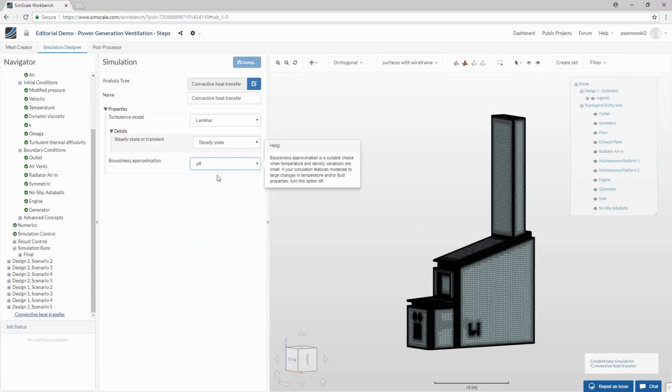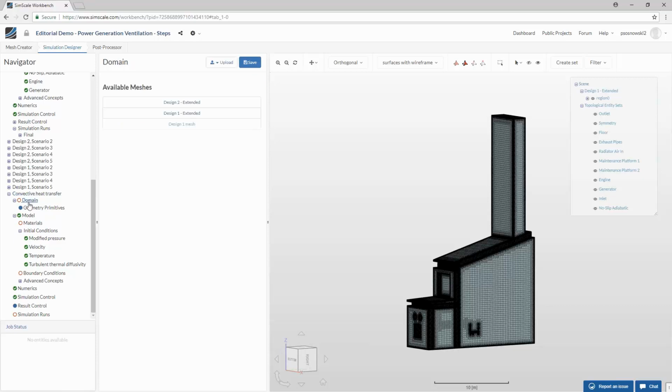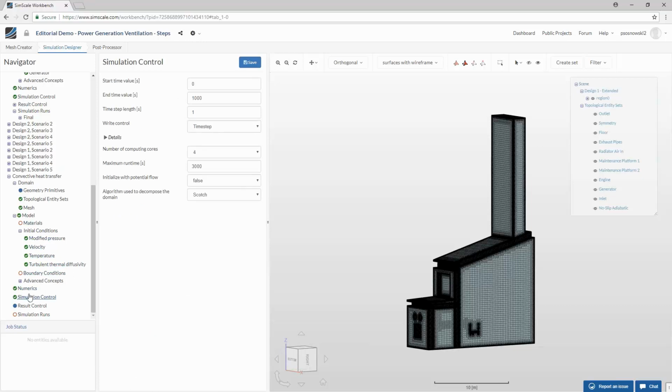And once I select the simulation type I want to work with, once it saves, what will happen is that you will get this empty template of your project ready to be filled. All you have to do right now is go from top to bottom, assigning every leaf of this simulation tree, entering it step by step, and making sure that your properties match the analysis that you want to run. Very straightforward, very simple, and always working the same way.